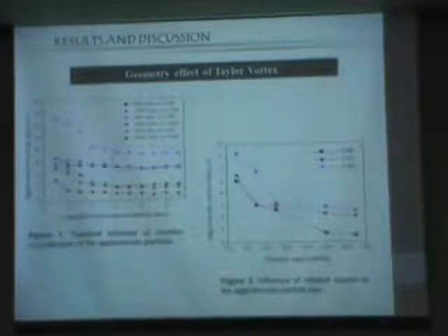After that, we can see that the agglomerate particle size decreases as the rotation speed increases for all cases, but it is stabilized around 6.5 micrometers for the geometry 0.93 and 0.89. Meanwhile, for the geometry 0.96, it stabilized around 4.5 micrometers. Why is this big difference? Because these conditions are in the turbulent regime. Meanwhile, this is for turbulent vortex regime. So we can see a big difference between different regimes and different vortex flow.